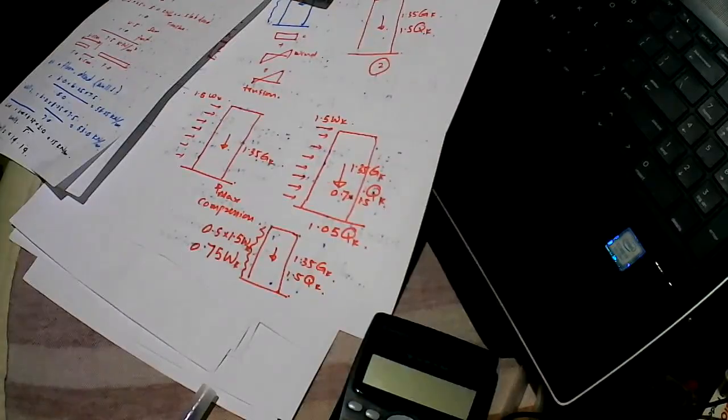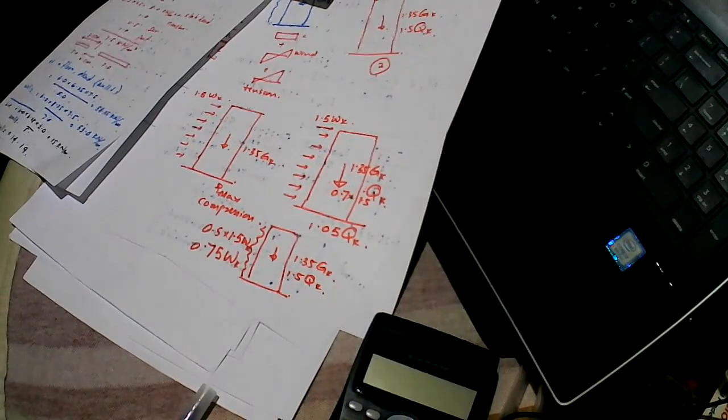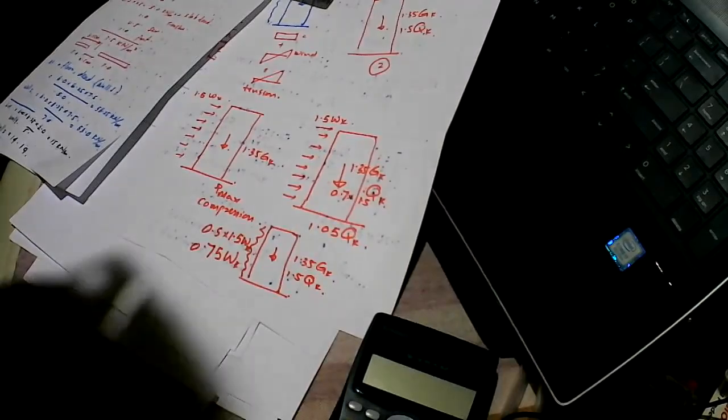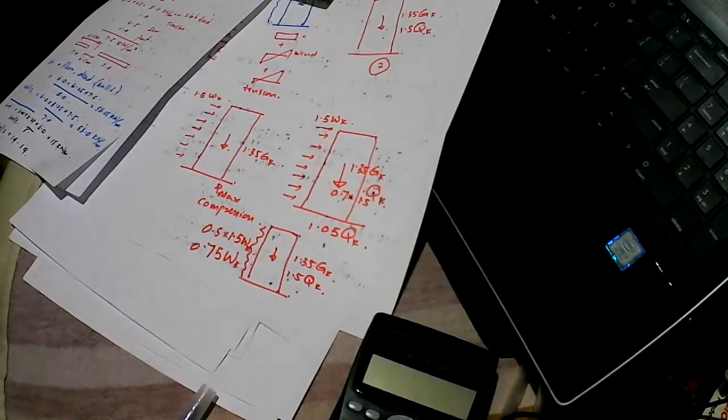In Eurocodes you get these variable actions and permanent actions. For variable actions, at a given time we will have one primary variable action, others will be secondary. And for wind, when it is primary, it's 1.5. When it is secondary, it is 50% of 1.5. For live loads, it's 1.5 when it's primary. When it's secondary, it's 70% of 1.5. 70% of 1.5 is 1.05. Is that clear?